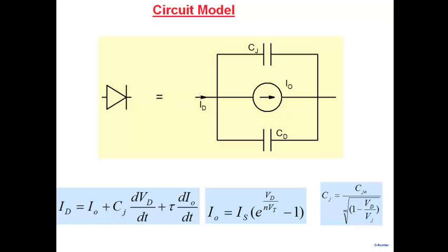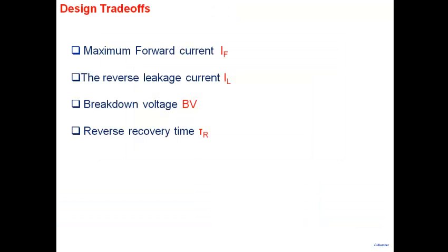But another thing that I would like to do is, when I look at a PN junction, after all the IV characteristics and everything that we do, I can characterize my PN junction with a set of important parameters. For example, how large a current can it conduct before it starts deviating from exponential characteristics? We would like to call this the maximum forward current. Every device will have a limit on how much current it can handle. If you go beyond that, it would start deviating from its ideal or normal characteristics, or if you go to very high currents, it may even get damaged.